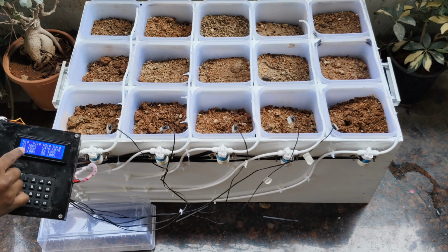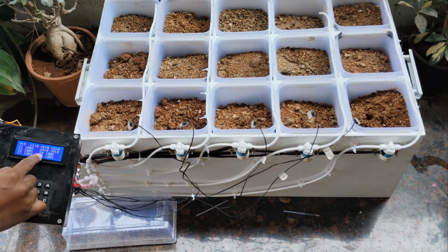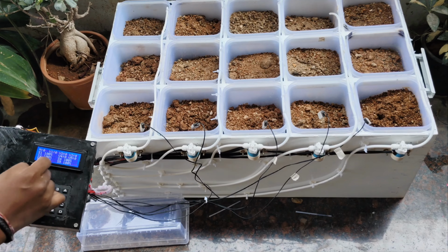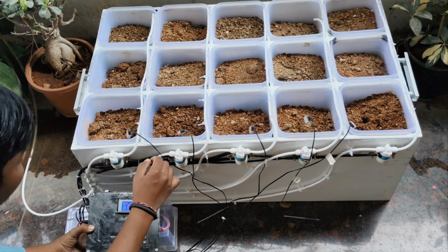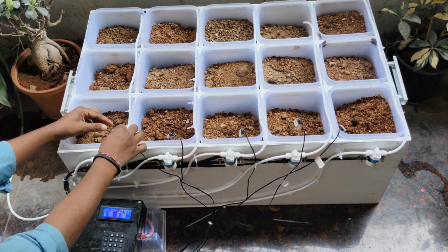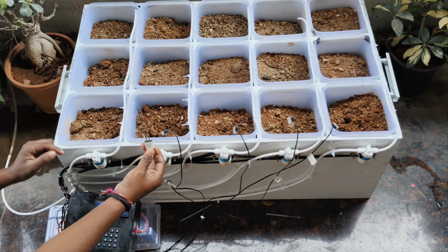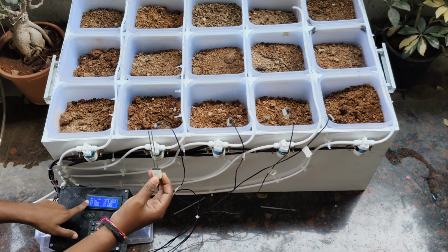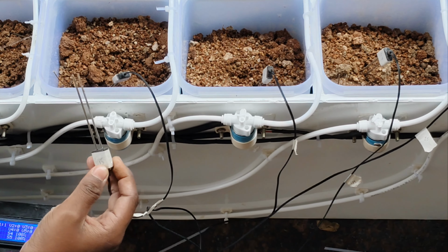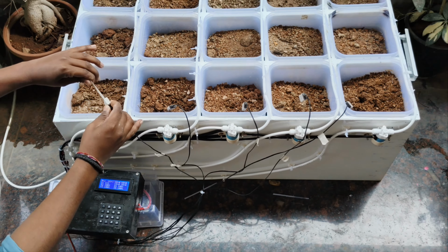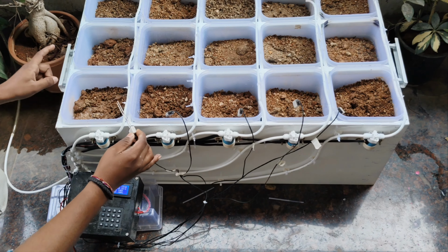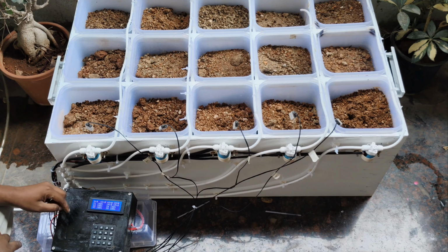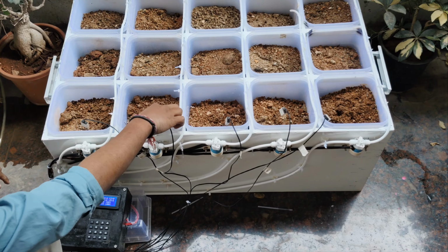You can see here S1, S2, S3, S4, S5, all the soil moisture content values are 100% and no valves are turned on. So I open any one of the sensors. Here I am opening soil moisture sensor 1. When I open it, it is watering the chamber because the soil water content is 0. The device thinks it is 0 and waters the chamber. When I insert it again, the water content is 100%, which is above 40%, so it stops watering.